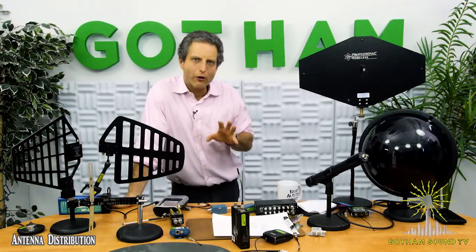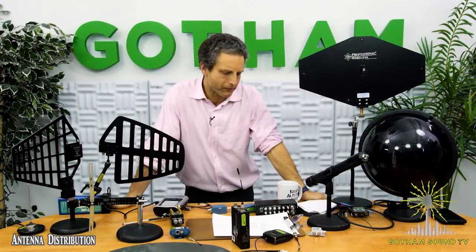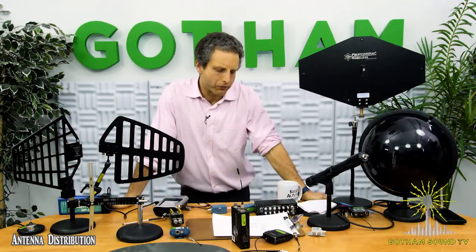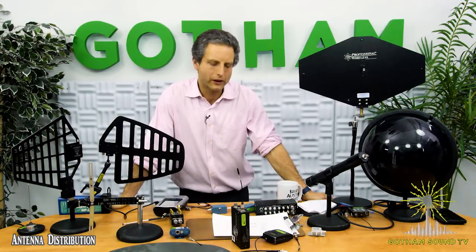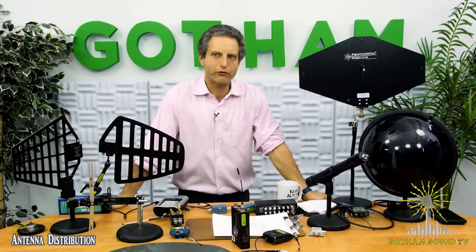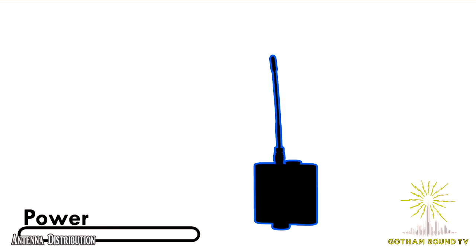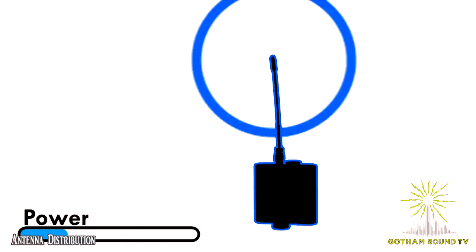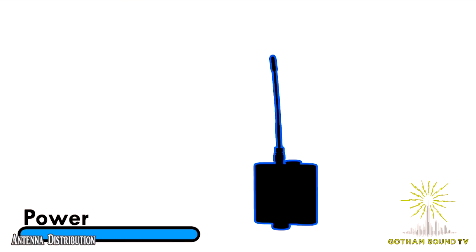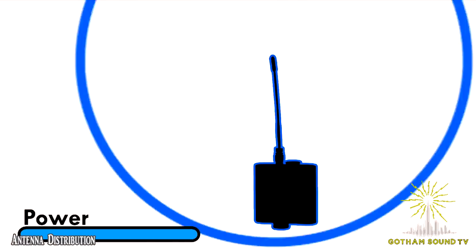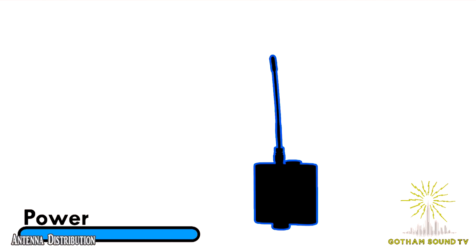But I think now is a good time to talk about, when we talk about RF distribution, we really have to talk about what's known as a link budget, and we have to start to think about how much RF gain is in our system. So Jared made an animation for us, and typical use case scenario for a cart, we have a power meter down below. There we go with our transmitter in perfect free space transmitting, and it's full power, but let's look at what happens.